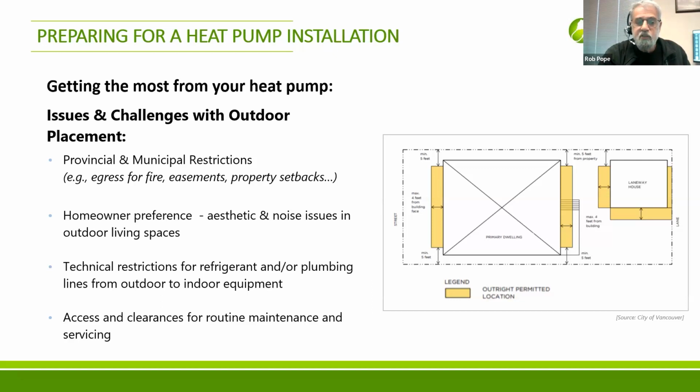And noise issues, you want to make sure that you're not going above, in a lot of municipalities, 45 decibels at the point of reception, in other words, your neighbor's property line. You can't exceed that. So you want to make sure the heat pump is at a spot where, at that property line to your neighbor, it's not above 45 decibels.